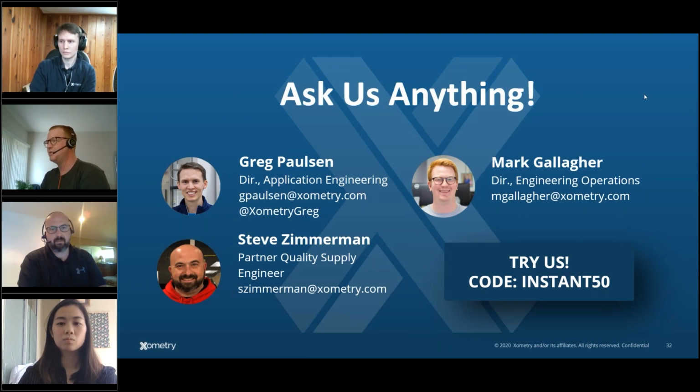If I see a drawing that has everything dual dimensioned in millimeters and inches, that's fine. It's pretty helpful, but be careful not to mix. Sometimes this is tough, especially if you're working with engineers transitioning between two systems. If you're going to use the metric system, that's great, but make sure that every single thing on the drawing is at least primarily dimensioned in the metric system.